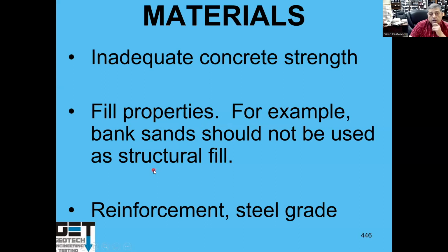Materials. Cause of failure can be because of bad materials: inadequate concrete strength, fill that's wrong. If you've got, don't put select fill in, or put sand underneath the floor slabs. Reinforcement steel: you put grade 40 where you need grade 60 steel.